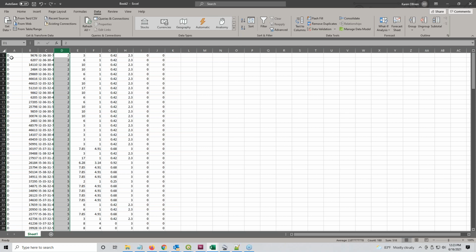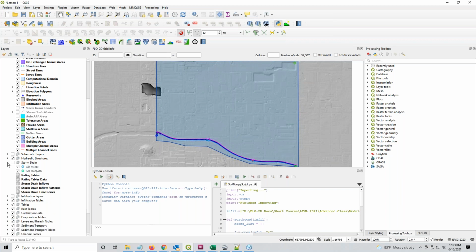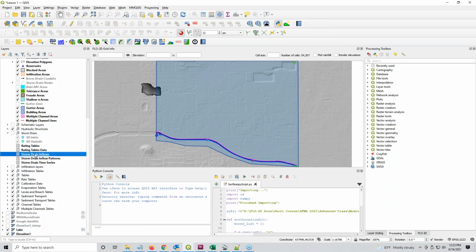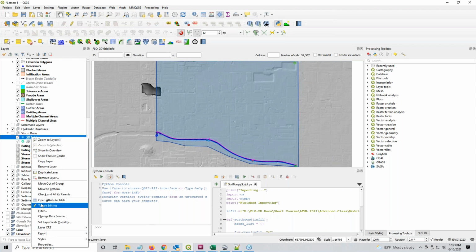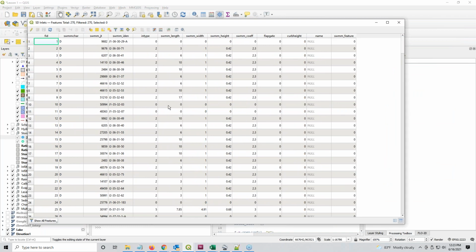If you want to do something to it here and you don't want to load it, bottom line is you can do your math here, you can do your editing here, or you can do your editing in QGIS. So you have the opportunity to look at the data in Excel, which is super easy, and everyone knows how to use Excel, so that's good. Or you can use the attribute editor, which we saw in the last class on how to use the attribute editor. And it also has its own calculators and things that you can apply calculations and scripts to.